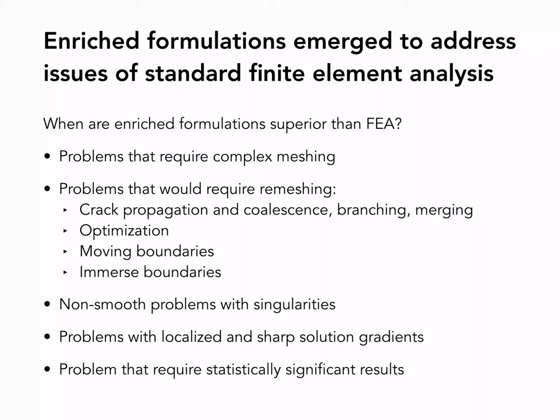Well, the last one is that these enriched formulations give you a remarkable property, which is mesh independency. This flexibility of not being concerned with the mesh at all can be used, for example, to obtain statistically significant results. Imagine you have a lot of different microstructure realizations, I'll show an example later, and then you need to obtain some average behavior. You can always use the same mesh, no matter what number of realizations you create. And so you can do statistical analysis to get results that are representative for that microstructure, if you will. Okay.